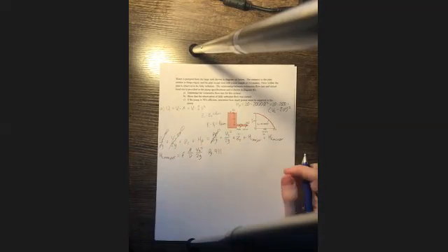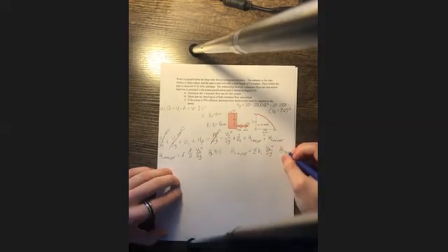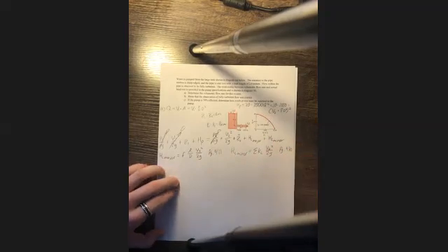I will be using this textbook as reference for this problem. Now the equation for head loss minor is the sum of the loss coefficients times velocity 2 squared over 2 times gravity. And this can be found on page 416.